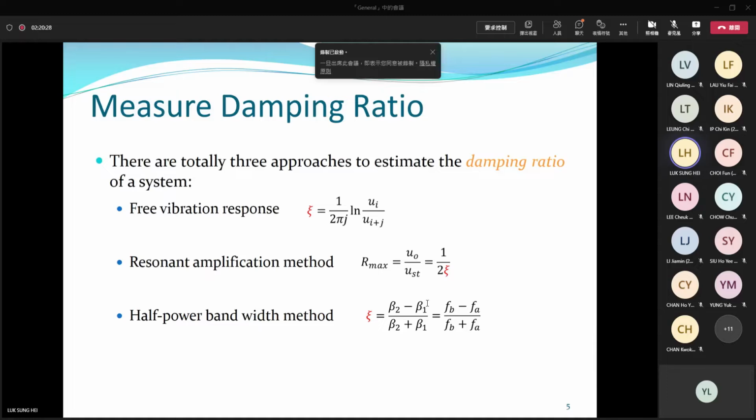In topic 6, we have a few applications. One application of harmonic vibrations is to evaluate the damping ratio. Damping ratio means energy dissipation. For structures, you have different ways to dissipate energy: due to cracks, due to yielding, due to friction, due to heat, due to many mechanisms. There is no theoretical formula to calculate damping. So here we use another approach. We use lab results to estimate the damping coefficients of some of our structures.